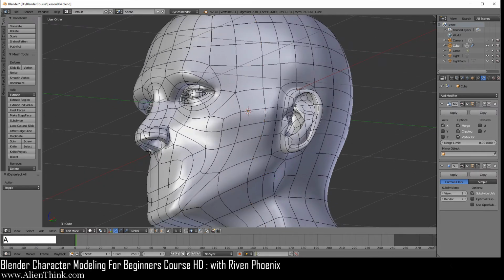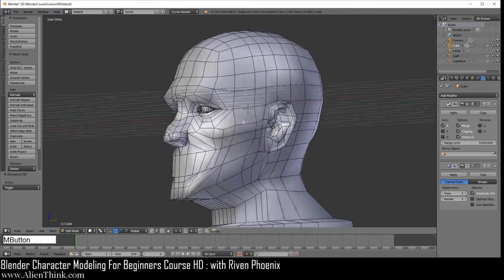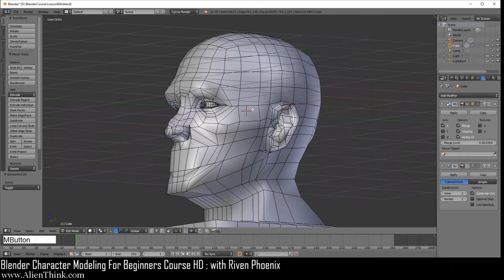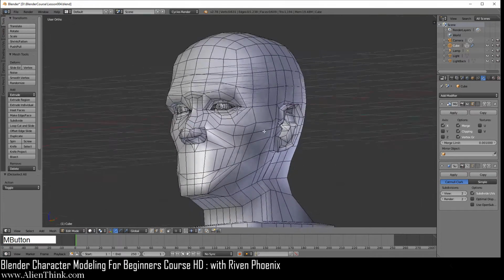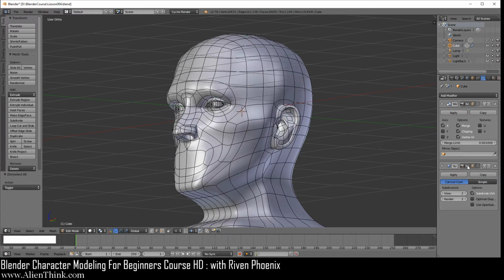As a test, what I'm going to show you first is I'm going to shut this modifier off. I'm just going to click on this eye over here. So you can see that this is really our original 3D model, and it's super low resolution over here, but this is really a useless 3D model. What we really want is the model that this subdivision modifier is going to give us. So under the subdivisions, under view, I'm just going to click on this one over here.